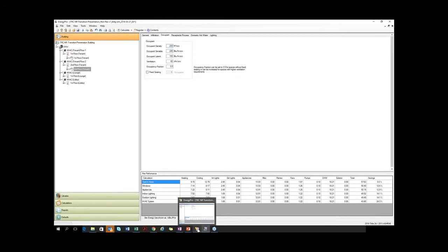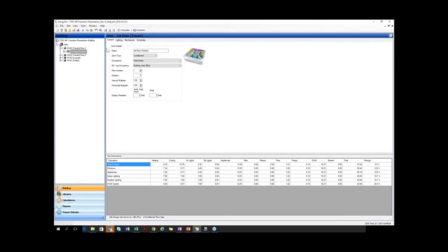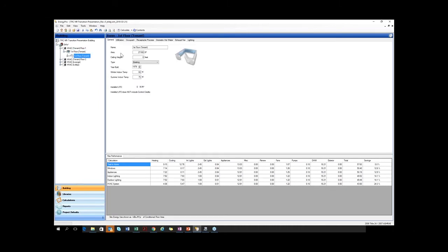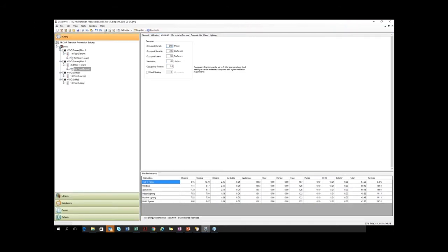So I'm going to open up the version 5 residential calculation. You see that the load assumptions here are basically the only difference is the feet squared per occupant. The DOE 2.1 algorithm in the non-res calculation is optimized to run with an occupancy density of 140 to 260 feet squared per occupant. Outside of that, it doesn't perform the way it should. So that's why we have to make sure we update that.